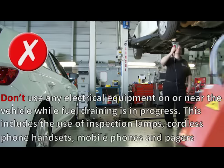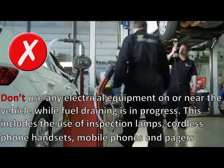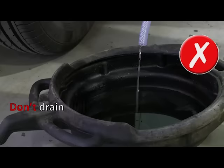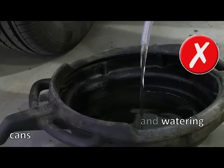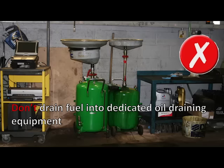Don't use any electrical equipment on or near the vehicle while fuel draining is in progress. This includes the use of inspection lamps, cordless phone handsets, mobile phones and pagers. Don't drain fuel into open-topped containers such as buckets and watering cans. Don't drain fuel into waste oil tanks. Don't drain fuel into dedicated oil draining equipment.